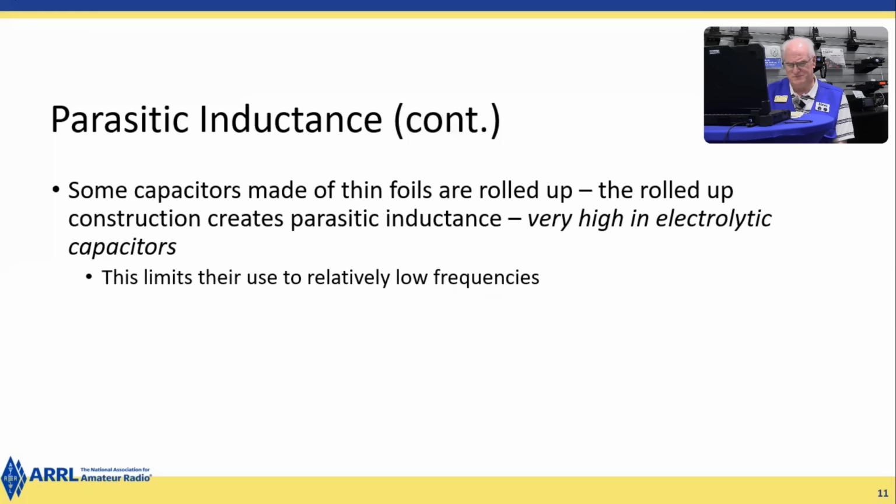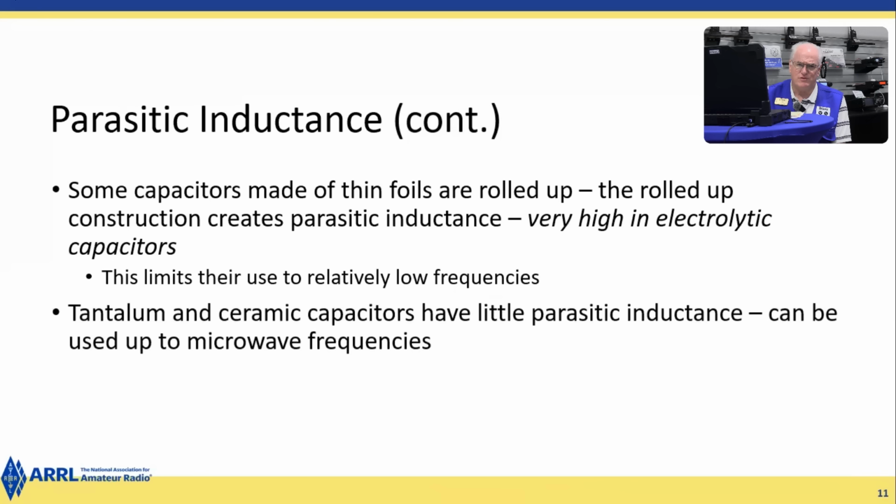Some capacitors made of thin foils are rolled up. The rolled up construction creates parasitic inductance. It's very high in electrolytic capacitors. This limits their use to relatively low frequencies. Tantalum and ceramic capacitors have little parasitic inductance and can be used up to microwave frequencies.